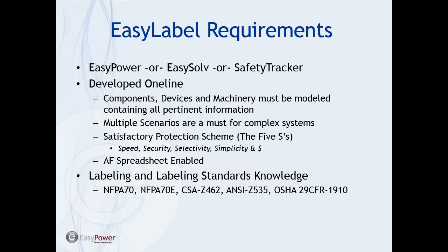This really includes all of the components, devices, and machinery. It's anywhere from actually knowing what the device is to the details of the transient response in the system on, say, a given generator or motor. Because pretty much anything that is moving in the system is going to be providing some sort of arc flash contribution.